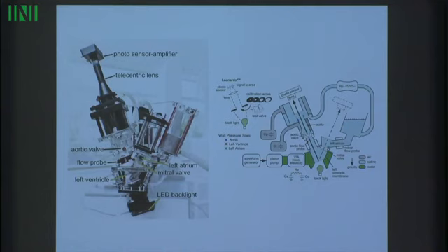It's a relatively straightforward flow loop. It has a rigid left atrium. You can put in a mitral valve. You have to put in a mitral valve. It's got a flexible bag, I'll show you a video in just a second, that represents the left ventricle. The whole thing is actuated by a computer-controlled piston pump. There's an outflow tract, an aortic valve, and an ascending aorta that has an idealized aortic root geometry. The whole thing is hooked up to a Windkessel. It's a classical Windkessel, so it's a compliance and a resistance, and then the whole thing returns.